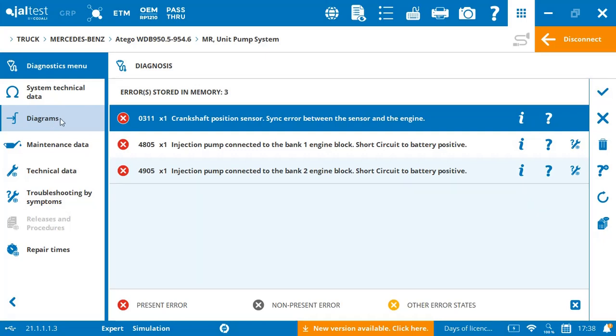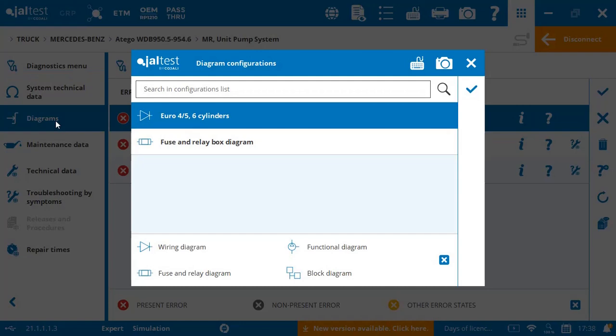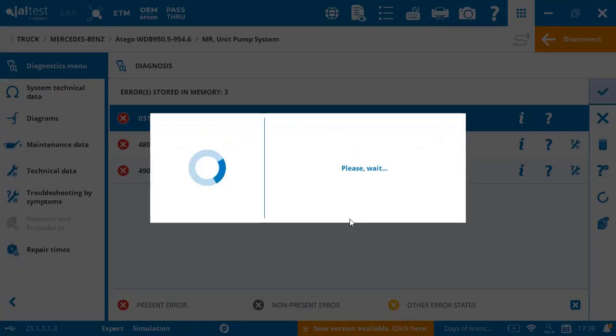Now, just a quick reminder that your diagrams, these repair manuals, you're only able to access them via Wi-Fi. So you must have Wi-Fi or a hotspot wherever you go. If your cell phone has data, you could make it a hotspot and connect to Wi-Fi with your laptop, so that you will be able to benefit from the repair manuals. So we're at a point where you took out the crankshaft sensor, you measured the resistance, and it looks good. So then what else? Well, you need to go to your wiring diagram here and check now to see if it's a wiring problem, which most likely it could be.